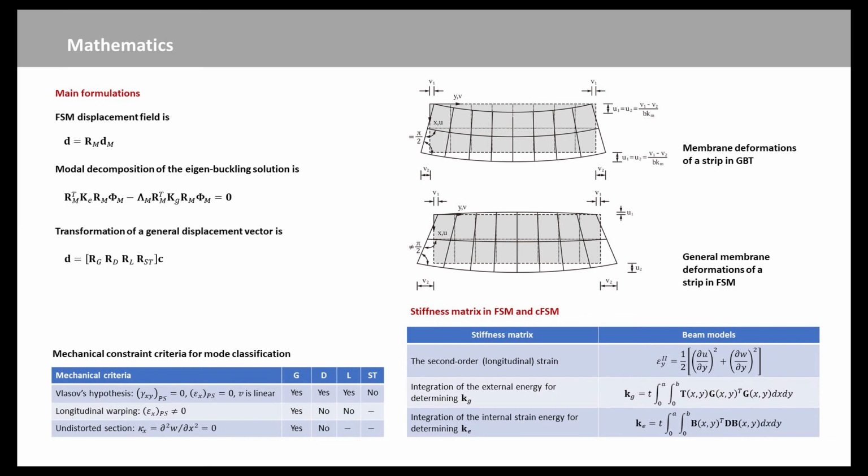The values of C are dependent on the normalization of the base vectors within R. Here, a simple vector norm is used throughout. This norm provides practically reasonable results. It's most consistent with norms used in general beam theory, GBT, and is most compatible with the application of CFSM in FEM model identification. Once the C is determined, participation in each mode must also be determined. The vector norm is used.